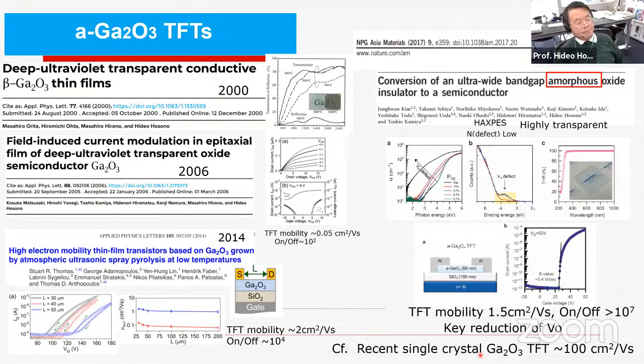What are the main challenges in making large area TFTs? Now the backplane of the large size display is shifted from amorphous silicon to oxide. IGZO is almost a standard, but the next challenge is higher mobility for oxide TFTs. The mobility of a stable IGZO TFT is maybe 15.